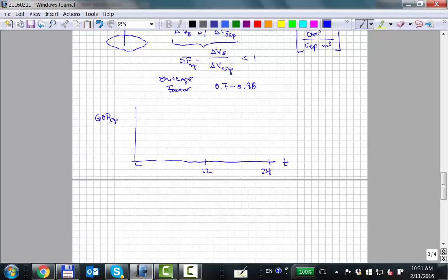during the early period here, this is what we call cleanup. Often they produce at a very high rate. There's a lot of water or mud. The metering is not very good, so maybe you've got a lot of scatter, like that. And then things start doing something like this, hopefully. Okay? So you see a stabilized gas-oil ratio. That's what you're shooting for, a period of stabilized gas-oil ratio.